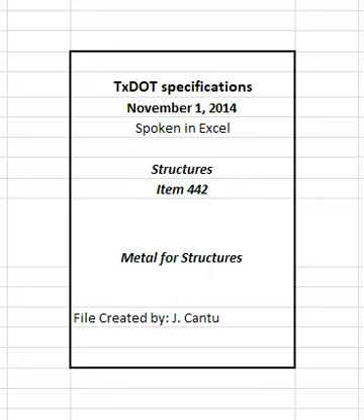2.1.2.1 Steel classifications. Provide the types and grades of steel listed in this section unless otherwise shown on the plans. 2.1.2.1.1 Carbon steel. Meet ASTM A36. 2.1.2.1.2 Low alloy steel. Meet the requirements of one of the following standards.